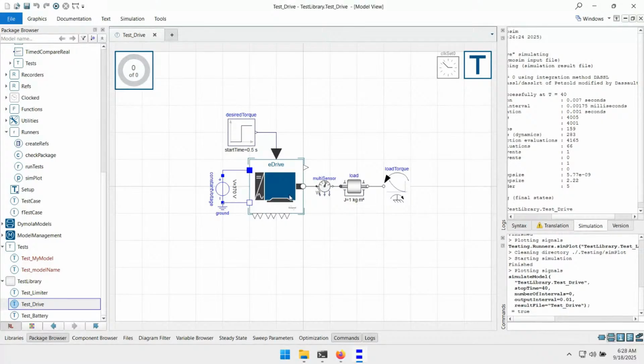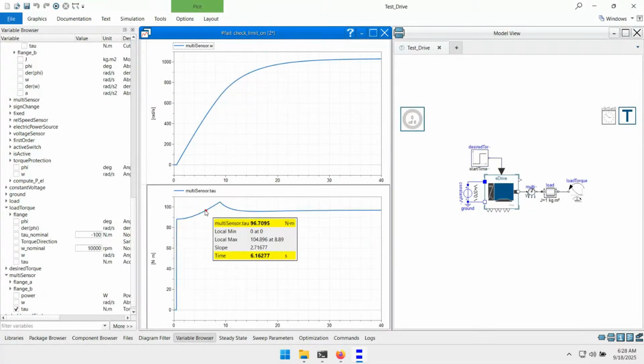And now let's see how we can test against that. So the problem is now, let me go back to the plot. If we look at this blue torque line, it's quite hard to provide a reference like this from a typical source block. So what we usually do is we simulate our models, then we look very carefully if everything behaves as it should, and at one point you will decide, okay, this is fine. This is now my reference result, and I will test all my future simulations against this reference.